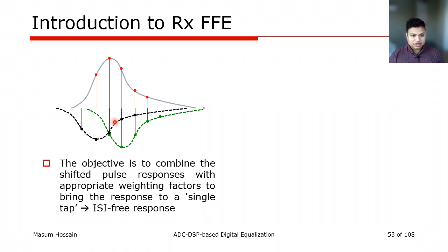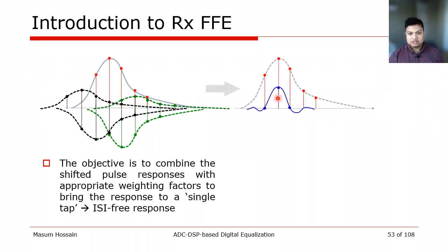More importantly, we see that the spread out pulse will also have its residue before it. That means we need to continue the process further to completely clean up any residue tail both on the precursor and the post cursor side. Ultimately, we will receive a pulse that is limited to a single tap, but the main will be significantly reduced.